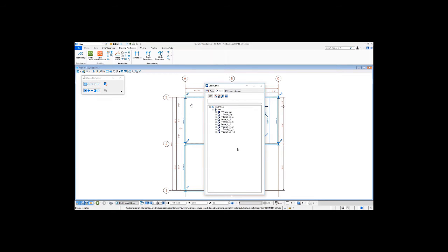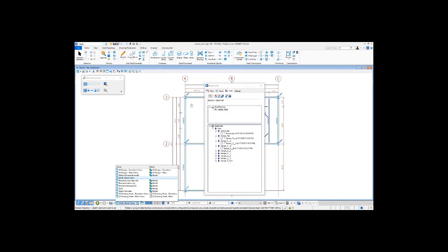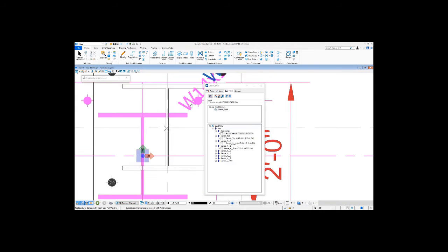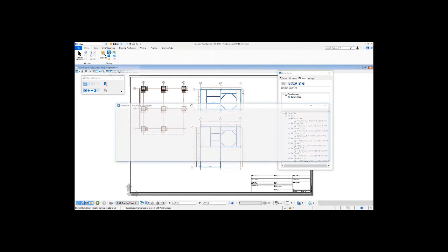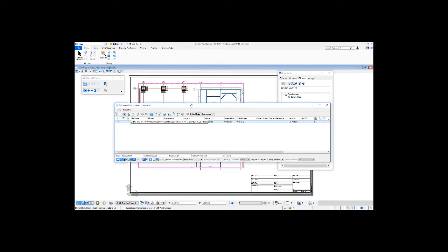Now it is time to insert whatever we saw in the preview into a title block or a border sheet. We can go to the insert tab and you can see all the views that are created. You can just pick them and add them to the title block. So you see we have added them to a title block.